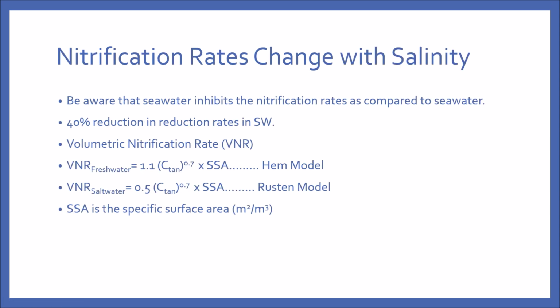It is very important to understand that nitrification in different salinity reacts differently. For example, you cannot just use the nitrification rates in freshwater and apply them to seawater, because in seawater, nitrification is much slower. It is estimated to be a 40% reduction in rates as compared to freshwater.